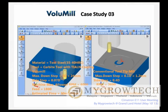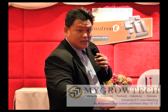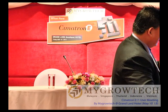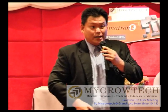Due to the machine and things like that, the maximum feed rate that I can go is actually 1008. Okay? The old way that the customers using the data, they are using a 1000 feed rate to cut. Okay? So this is the cycle time that we get. Our cycle time for this roughing process is around 30 minutes, 58 seconds. And the old way is nearly 1 hour. Okay? You can see a big improvement in cycle time.